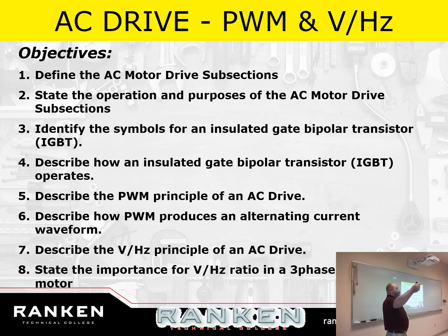When we mess with the frequency, we mess with that, which can raise or lower the amount of current that the motor draws. One of you yesterday, which one was it? We wound it up to about 100 hertz, 90 hertz, and you saw that the current draw went down to almost nothing, right? Because raising that frequency up above the rated actually killed the resistance in it.